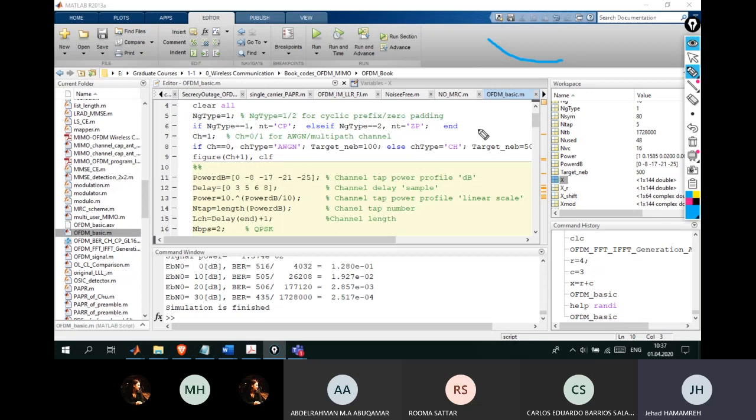Why is that? Because in OFDM, the main goal is to transmit a large number of data, very fast, or basically increase the data rate. This is the problem why we needed OFDM. You basically need to increase the speed of your internet, the speed of your data transfer. And when you increase the speed, the pulse duration shrinks, yes? It basically shrinks, and when it shrinks, the bandwidth increases, and since the bandwidth of the symbol is now greater than the coherence bandwidth of the channel, you get a frequency selective channel, and this frequency selectivity in frequency, in time, we call it time dispersive. So that's why it's realistic and makes sense to always simulate OFDM over a frequency selective fading channel if you don't have too much mobility.